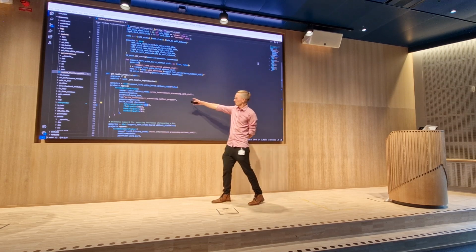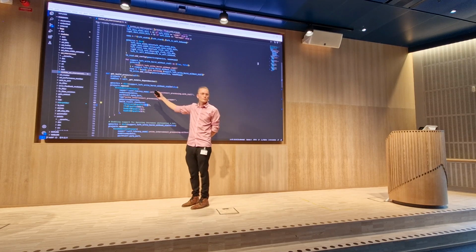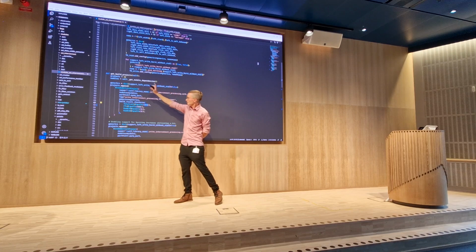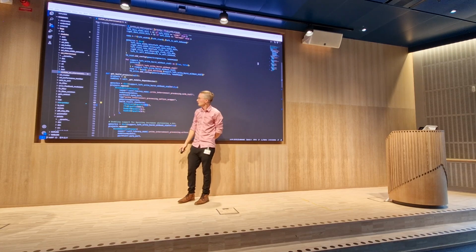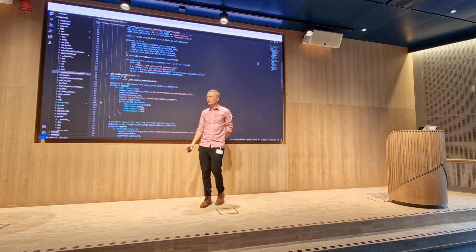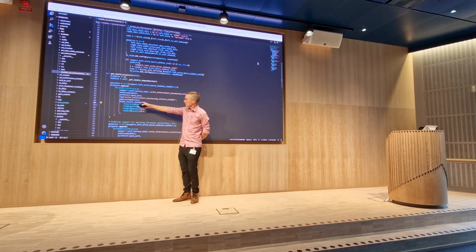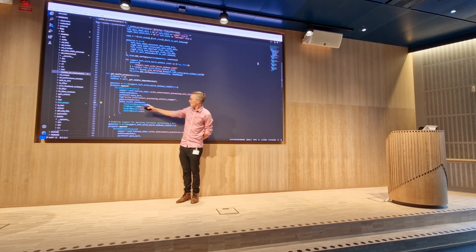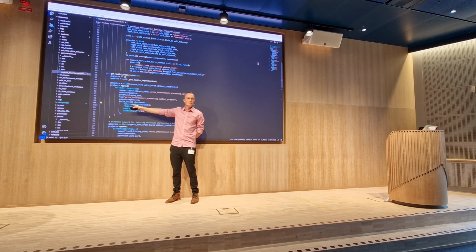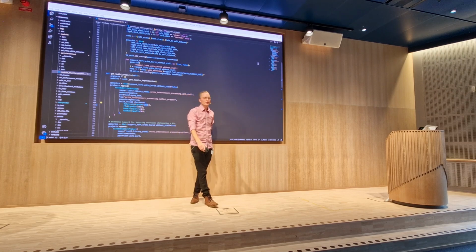So this is one of the projects that's currently building. We specify what kind of project it is, the top level we're using, any constraints if this is a real FPGA build. And here we have the build result checker. That in this case specifies the total number of LUTs should equal 352.